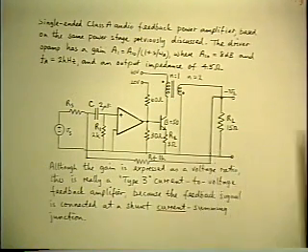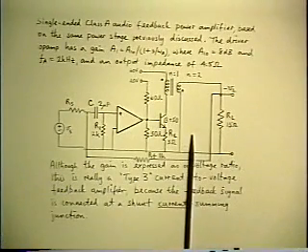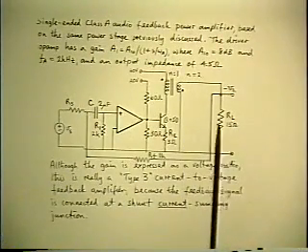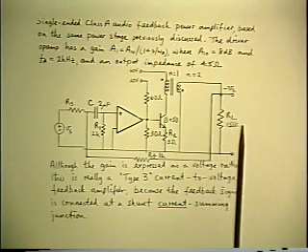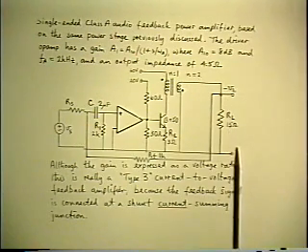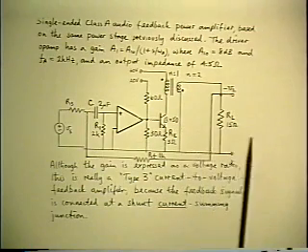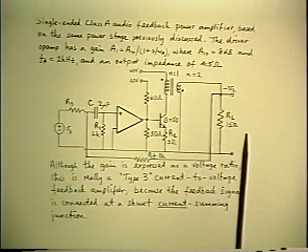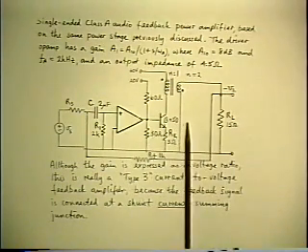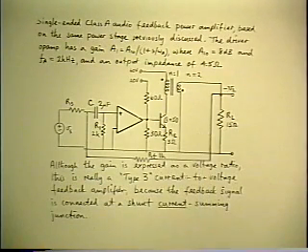Okay, let's calculate now the inside output impedance. Inside output impedance is the only one that matters in this case. Outside output impedance is of no interest because nothing else is going to be connected beyond the loudspeaker. So usually the audio amplifier is specified separately from its load. So it's the inside output impedance that would appear on the data sheet. So let's calculate ZOF.